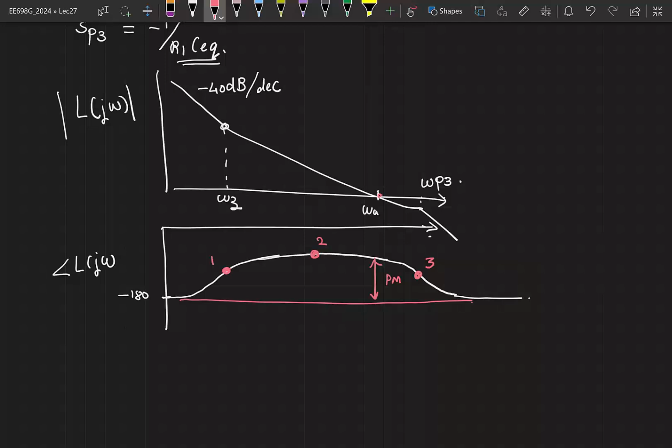So that you can get a larger bandwidth. So you are assuming omega P3 because this is if the VCO phase noise is a problem, right? But let's say you could have also pushed your omega P3 out, such that the region still extends flat like that. So I want to know, given this phase graph, is there a reason why you would keep it here, here or here? I think most probably